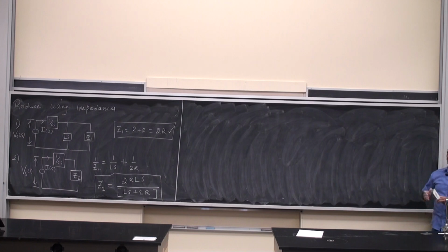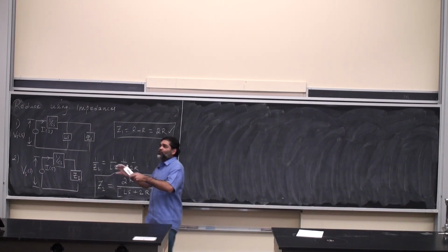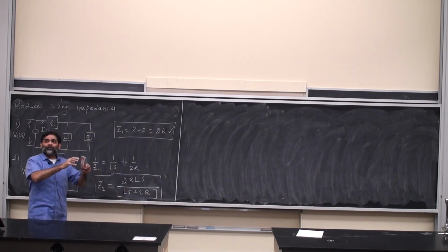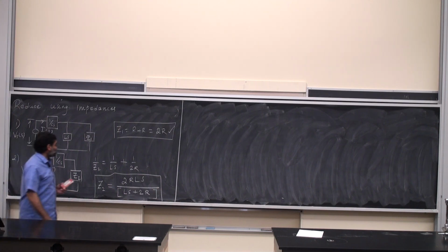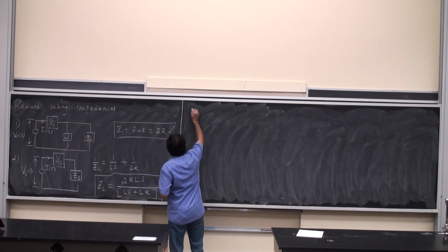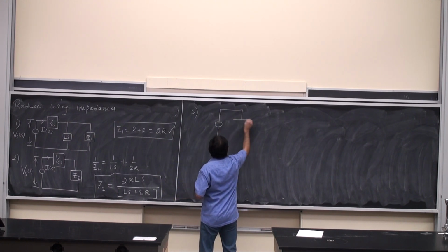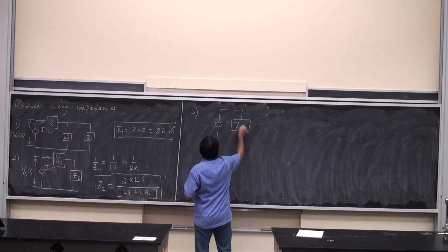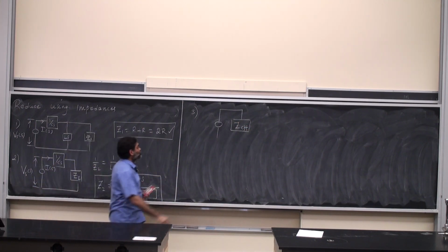No matter how many branches you have, this is like working on a problem in trusses. You start off with one and then you slowly work your way back to the member or the truss bar that you need. Okay, so same idea here as well. And obviously you see these are all in series, so I replace them by my third step, the third reduction. This is now Z effective, right, which is what we are looking for.